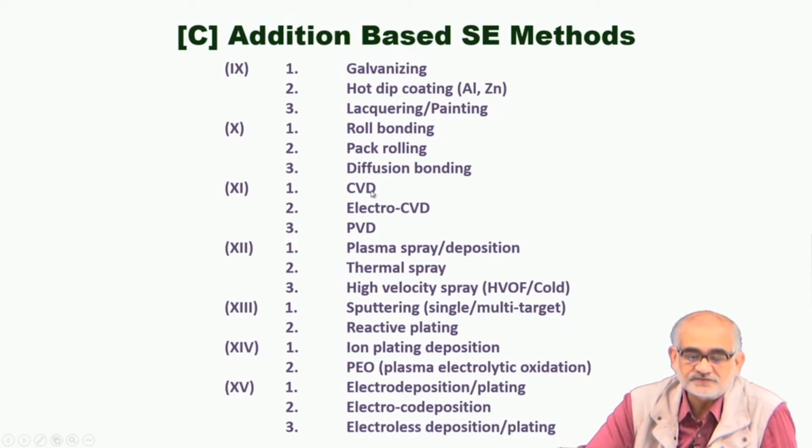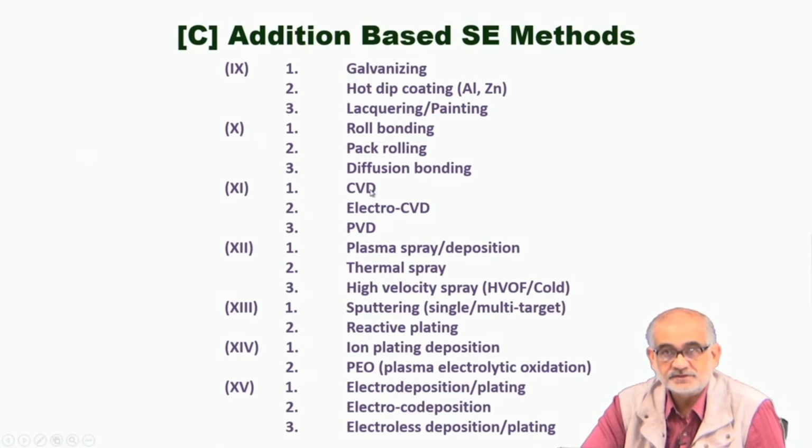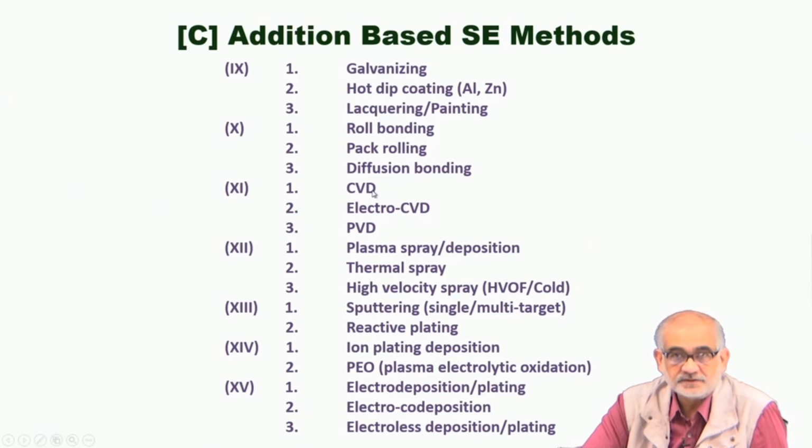The difference being that in CVD there is a difference in the composition that you develop onto the surface, because the deposition also includes a certain limited level of reaction happening either in the vapor state or after arriving onto the surface, mostly in the vapor state itself.